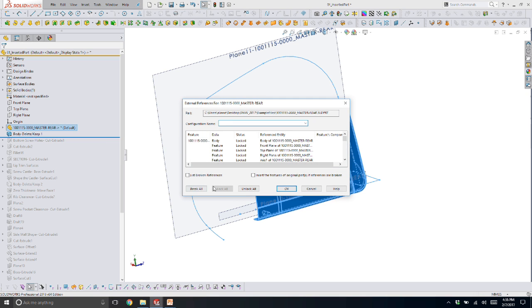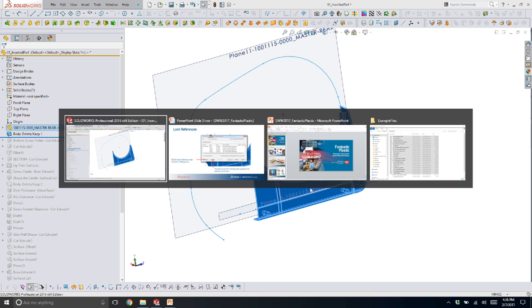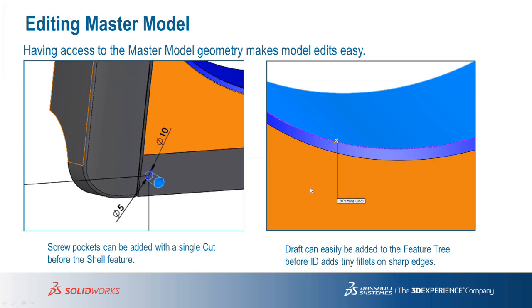One thing I never do, and I potentially run into some situations where PDM software requires this, like a third-party, not SolidWorks PDM system, is break the references. Because once they're gone, you never get them back. So the break is a one-way, and you also get a big X in your tree here, and you can never get rid of the X in it. You know, who likes a big X on the top of the tree? That's my recommendation, would be locking those external references, not breaking them, to save yourself the rebuild time.